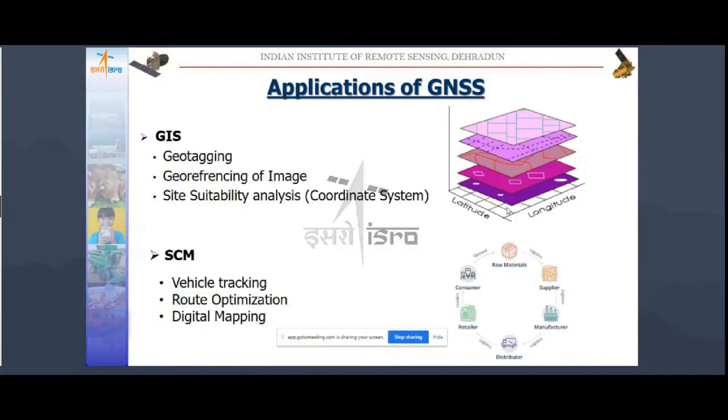We need some reference points, after which we can interpolate and assign coordinates to each pixel of the digitized image. We get these coordinates from the GPS receiver. We go to some known location which is also visible in the image, and in real time at the site we collect the coordinates using the GPS device, and then enter them into the GIS for that digitized image.